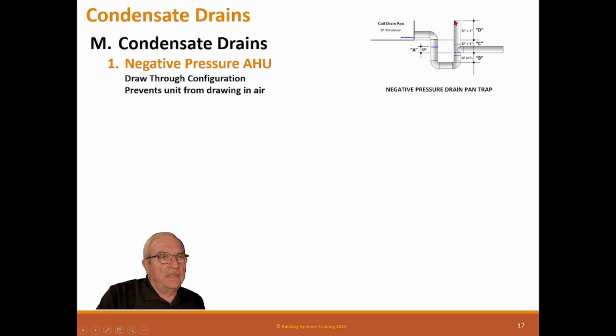Now, some engineers design condensate traps all kinds of ways, which is unfortunate because condensate traps are designed from physics, not from any designer's intentions. So if you don't design them like this shows, they're probably not going to work. This trap has to be low enough and deep enough so that the pressure in here can't suck the water right into the unit. So that has to be deeper.